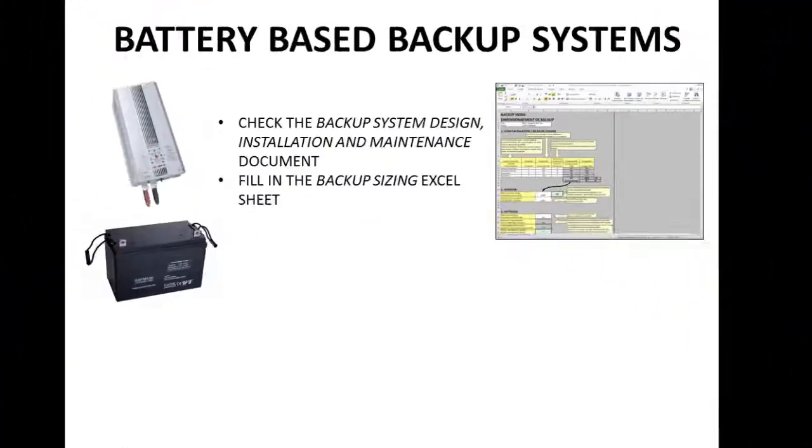As explained at the beginning, although backup systems are not exactly an energy source, we will introduce them in this video. A backup system is composed of a charger inverter and batteries. As the name states, it is intended to be an energy backup, to be used whenever there is a city power cut and or the generator is not running. In some locations a generator is needed during the day, and at night the power needs are much lower, so a backup system will be enough. This will release us from having to run the generator too many hours unnecessarily.